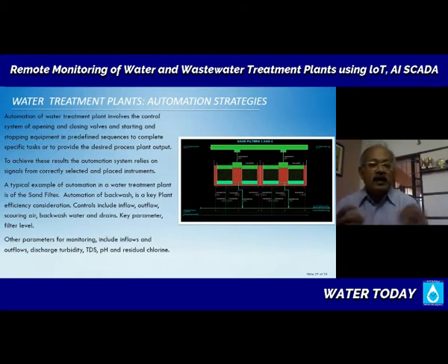And then to disengage the dirt from the sand, you also use what you call a scouring air system. Now, this whole process, from the time that you close the inlet of a sand filter to allow the water to drain out, and then close the filter discharge, then allow the water to come in from the bottom, which is the backwash water.